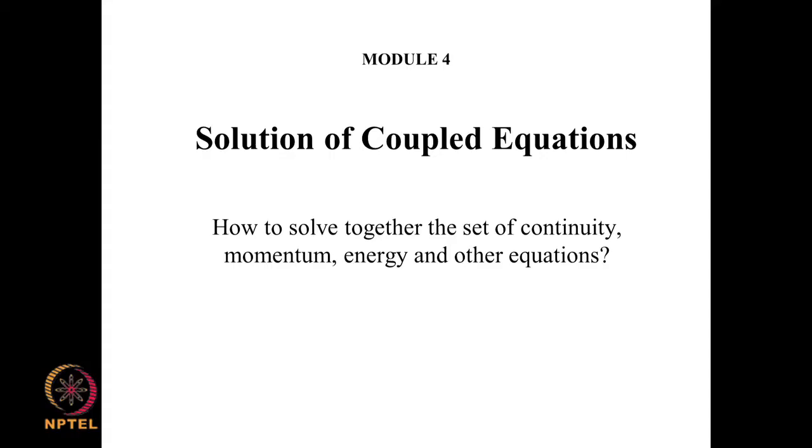We are into the second part, part B of module 4, and we are concerned with the solution of coupled equations, and that is a question of how to solve together a set of continuity, momentum, energy and other equations, but for the specific case of incompressible flow. We know that incompressible flow is not a property of the fluid, but it is a property of the flow.